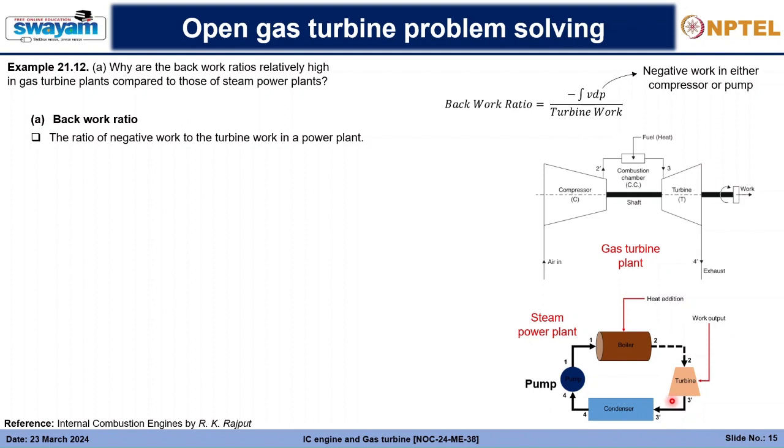And when the steam expands, it goes either to a still superheated state or a wet state at a lower temperature, lower pressure, and that lower pressure steam is going into the condenser, where the condenser will remove the excess amount of heat enthalpy from the steam, and accordingly this steam will return back to its liquid state, that is water, and that water is again pumped to the boiler using a pump.